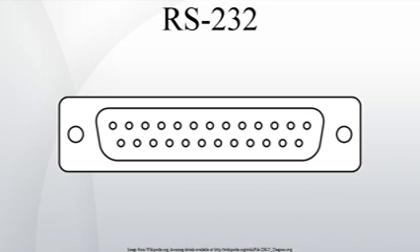Seldom used features. The EIA-232 standard specifies connections for several features that are not used in most implementations. Their use requires 25-pin connectors and cables. Signal rate selection. The DTE or DCE can specify use of a high or low signaling rate. The rates as well as which device will select the rate must be configured in both the DTE and DCE. The prearranged device selects the high rate by setting pin 23 to ON.